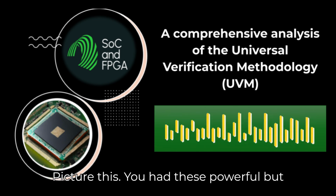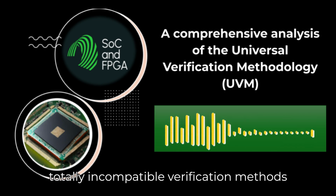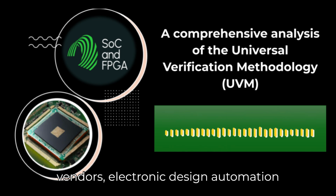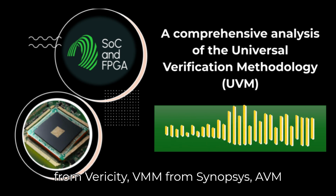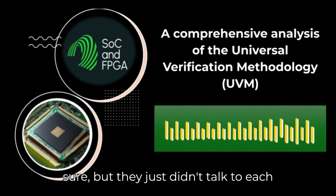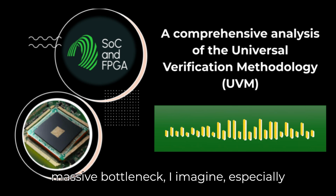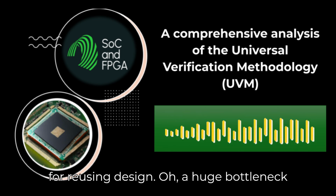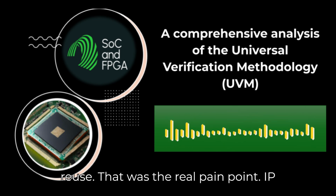Picture this. You had these powerful but totally incompatible verification methods popping up from the different EDA vendors, Electronic Design Automation companies. You had things like eRM from Verisity, VMM from Synopsys, AVM from Cadence. Each was good on its own, sure, but they just didn't talk to each other at all. And that created a massive bottleneck, especially for reusing designs. A huge bottleneck for intellectual property, or IP reuse. That was the real pain point.